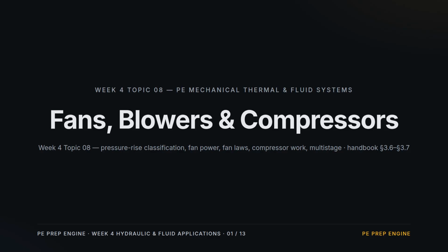Topic 8 of Week 4. Fans, blowers, and compressors. The machines that move gas instead of liquid. We classify them by pressure rise. Treat fans and blowers as incompressible, where the pump equations carry straight over. Run the fan laws, then cross into compressible territory for compressor work. And finish with why we stage compression and cool between stages.